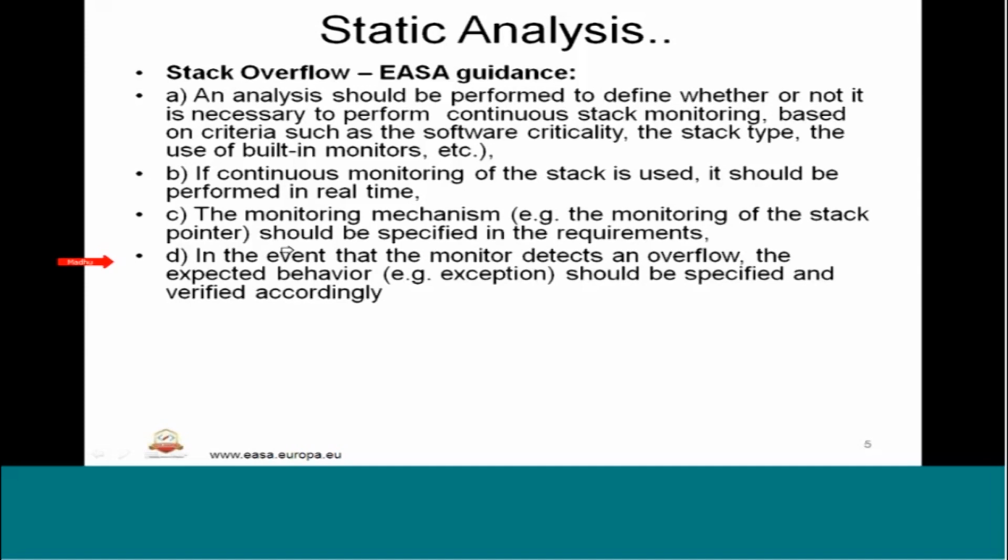In the event that the monitor detects an overflow, the expected behavior, meaning an exception or an interrupt, should be specified and verified accordingly. That means if there is an issue with the stack, such as overflow, it needs to be mitigated within the program with the expected behavior of raising an exception.